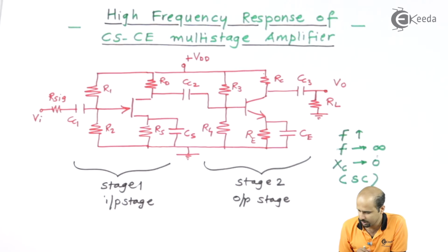No, not really. This is because there are a few more capacitances, called intrinsic capacitances, and when these intrinsic capacitances become short circuited, they can affect your operation as an amplifier. They will not give you the gain which is required from a customer's point of view.